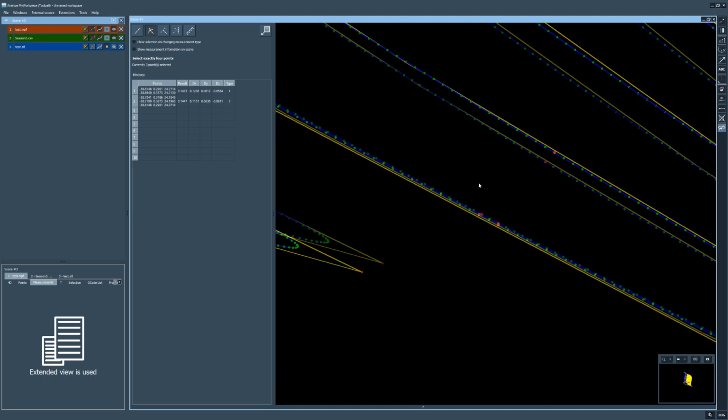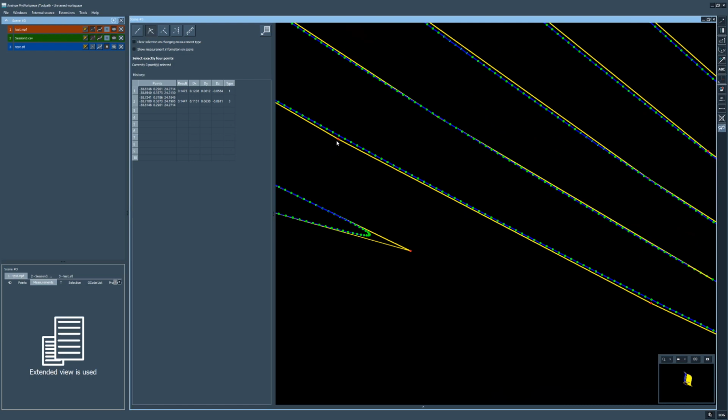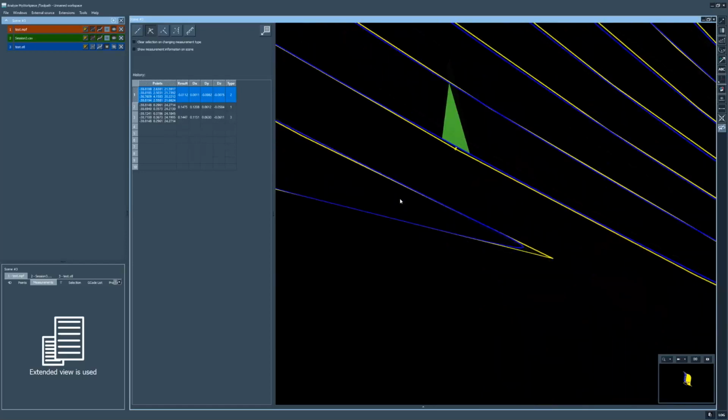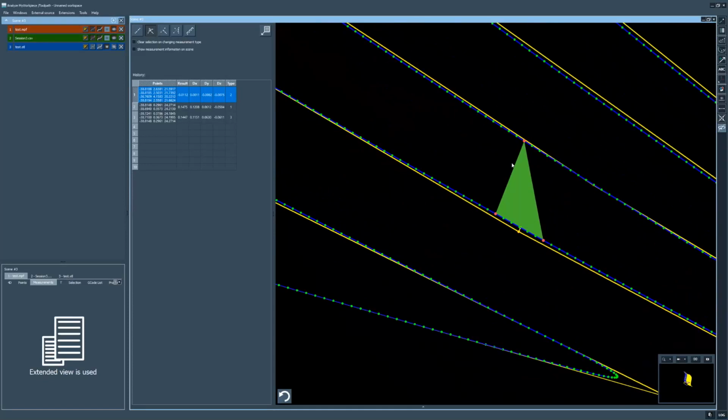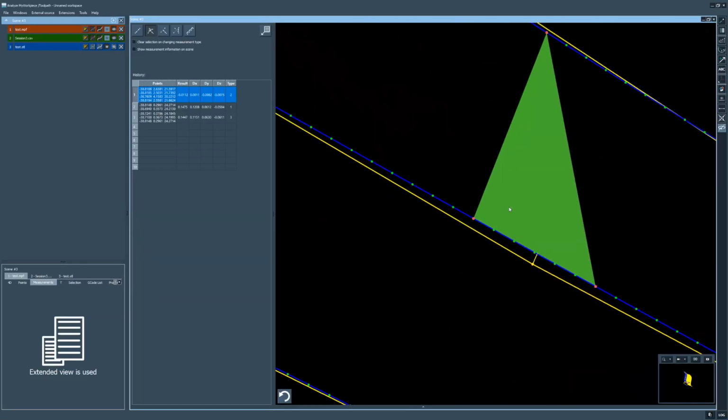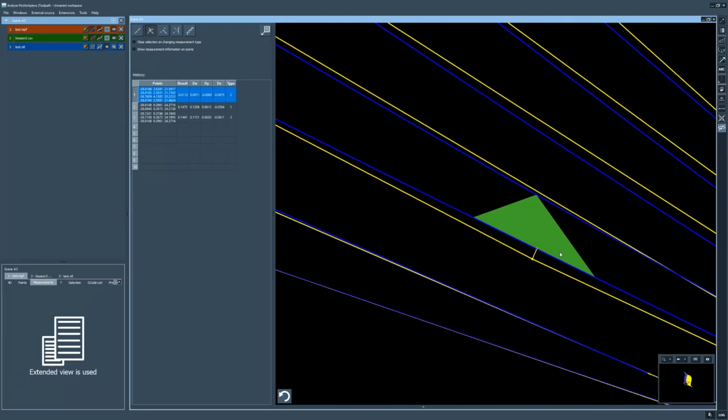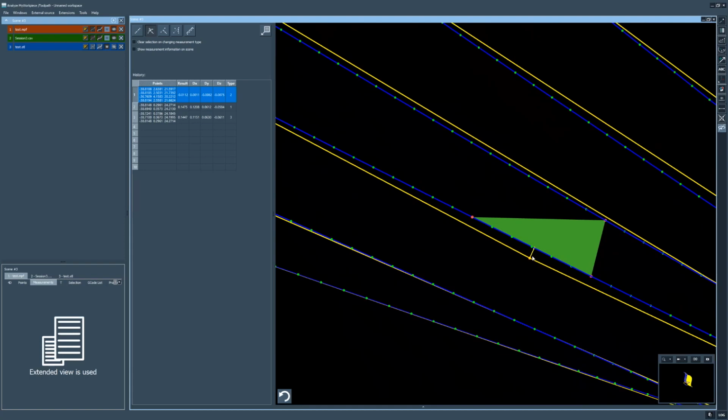And then the next point we are clicking. Okay, this is maybe not so good. Let's take it from here. 1, 2, 3. And the 4th point we select is the point from which the distance is calculated. So what did Toolpath now do? Let's just rotate a little bit more helpful. So this green one is now the plane that was created by Toolpath, selecting the 3 points. And then we see this yellow line here. This is showing me the distance between that plane and the point. We can also see the result again here in millimeters and the XYZ component.